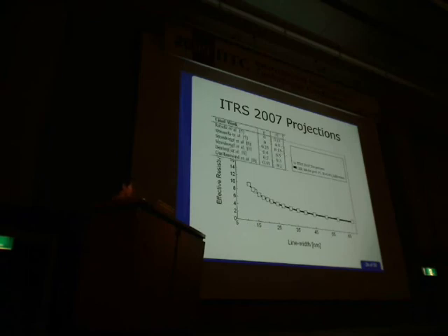If we compare this to the data and to ideal parameters, the R value seems to be okay. But look at the model parameter P, which is specularity. Remember I said that if P equals 1, as the electrons encounter the sidewall, they should experience some kind of drift velocity loss, some energy loss. We're clearly seeing more of an elastically scattered event here, higher than what's actually in the data. So that's something to consider as well.